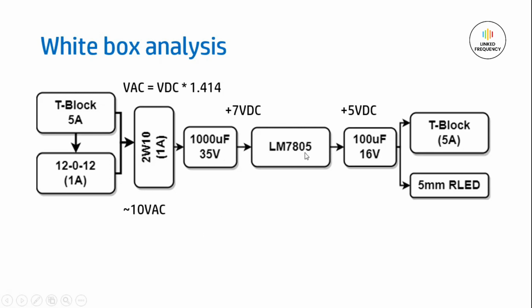But in case of a 12 volt regulator, at that time you need to use at least an 18 volt transformer at the input side. To ensure proper functionality of the entire circuit, make sure that you use these formulas and calculate the minimum input AC voltage for the bridge rectifier. Accordingly, select the proper transformer.